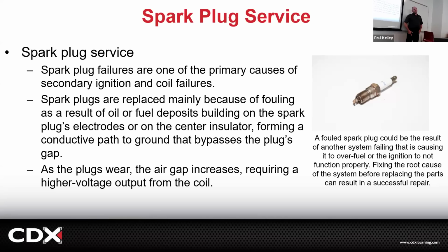There are more than one way. Back in the day, I wouldn't do this because labor is expensive compared to spark plugs, right? But back in the day, they used to have a little sandblaster, and you could put some sand in this little pouch, and you could screw the spark plug onto it, and you could hook it up to an air hose, and it would basically sandblast the spark plug. It would just clean it up. That would fix the fouling. That's kind of cool, huh? You know why we don't do that?